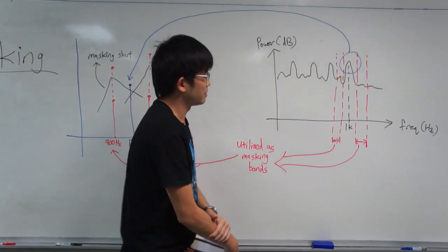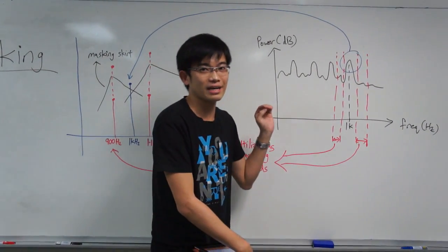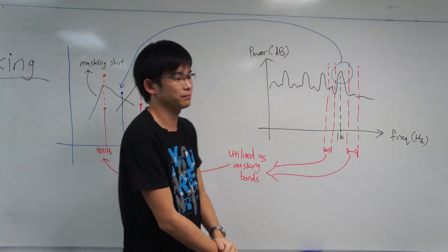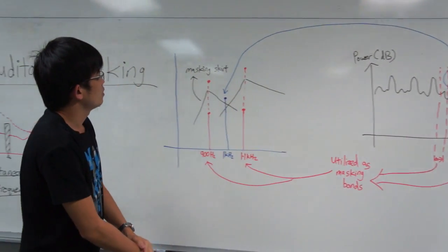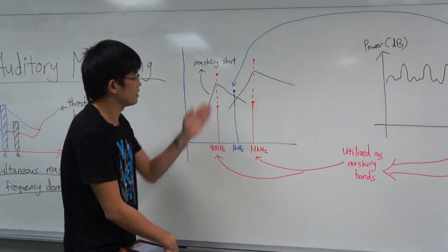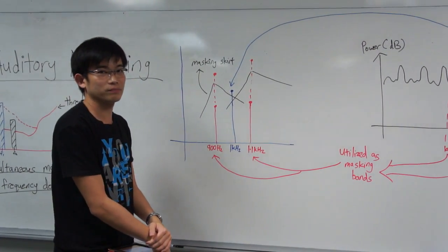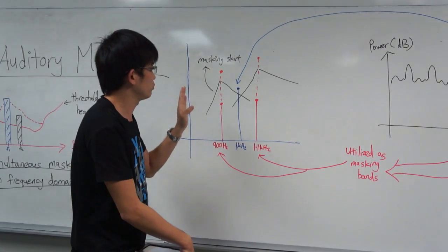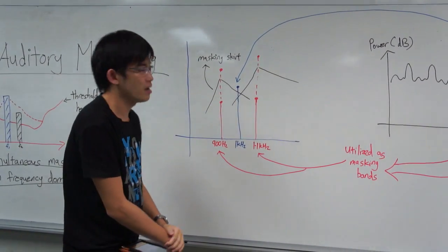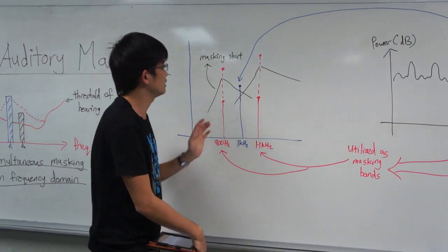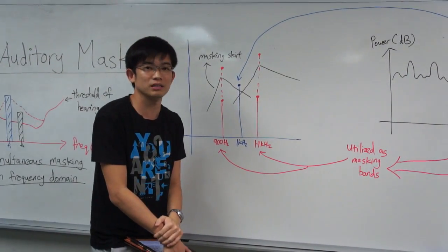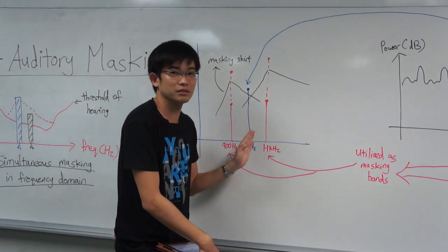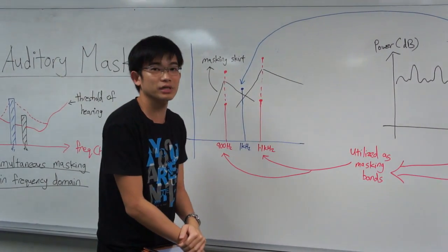To further illustrate our ideas, we choose 1 kHz tones as an example because the 1 kHz tones is also the most significant tones that exist in the musical signals. So let us look at the masking skirt. In this diagram, the masking skirt shows that it can mask out more higher frequency components than lower frequency. So based on this concept, we decided to choose the lower adjacent signals to be a masker to mask out the 1 kHz tones. But after going through a certain amount of testing, we realized that this masker is not sufficient to mask out the signals due to the fluctuations of the signals. Therefore, we decided to use the higher adjacent signal, which is 1.1 kHz, to complement the 900 Hz masker with a significant gain increase.